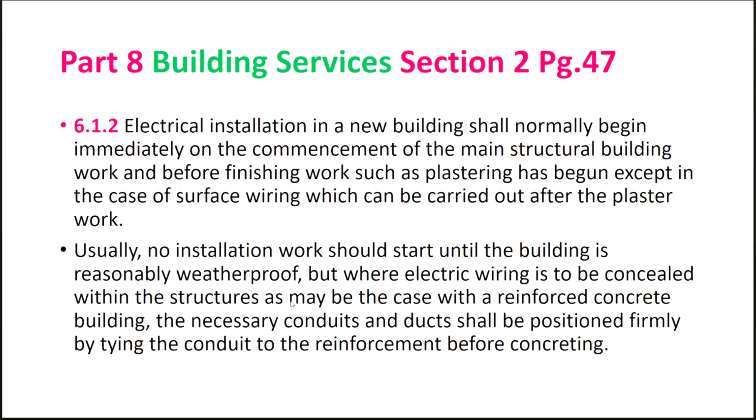But where electrical wiring is to be concealed within the structures, as may be the case with a reinforced concrete building, the necessary conduits and the ducts shall be positioned firmly by tying the conduit to the reinforcement before the concreting. But again, it is silent with respect to the structural integrity. It is trying to tell how it is to be done.